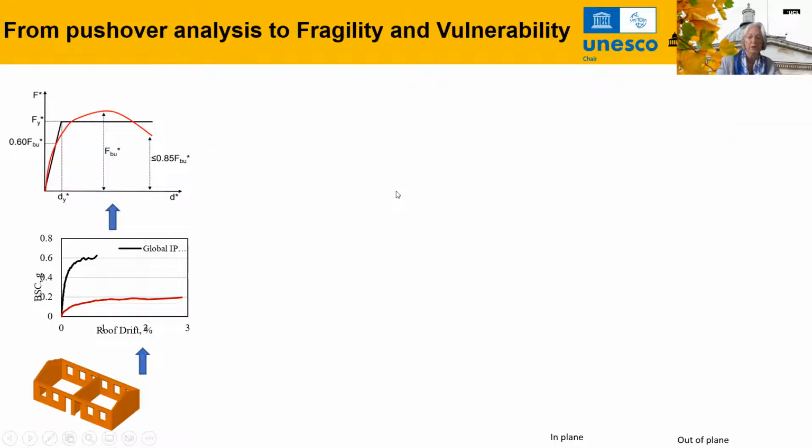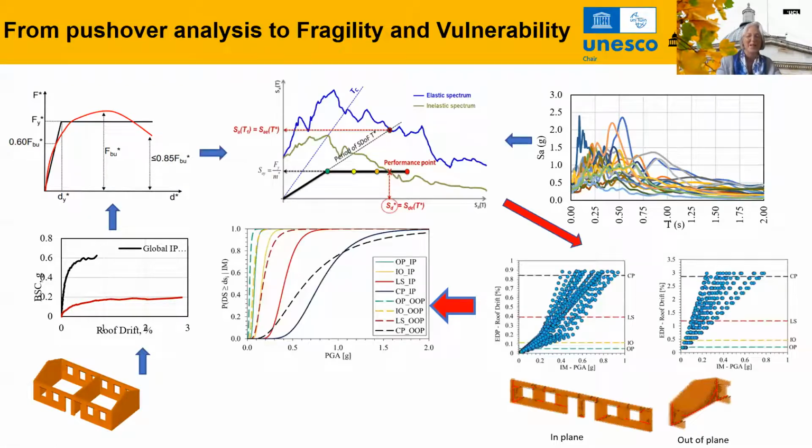And then we will use some analytical formulas in order to arrive at a family of different fragility functions, which basically tell us the probability that a given earthquake, represented with a specific intensity measure, for instance here, peak ground acceleration, has a given probability of occurrence for a different level of damage.